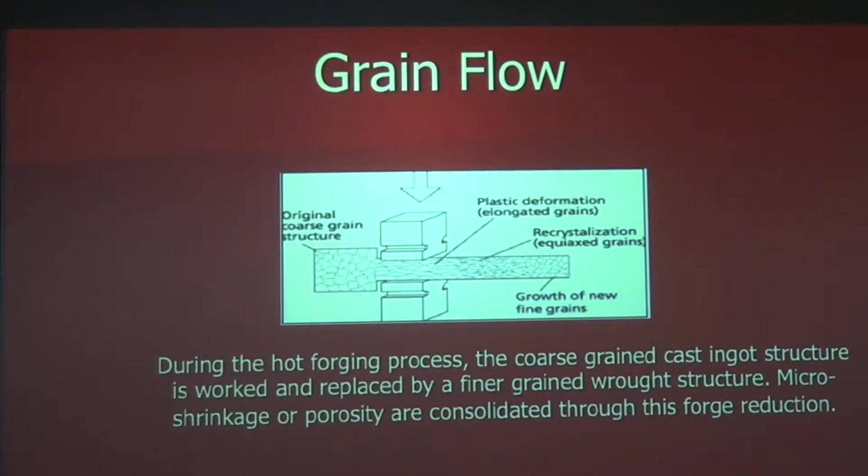That difference in properties is related not only to the change in microstructure, but also to the fact that you're almost always going to have some amount of non-metallic material in the steel. We can talk about why that is a little later, but just accept that it's there, and those non-metallic particles can be stretched out and elongated a little bit like taffy. That is why you get directionality in properties.